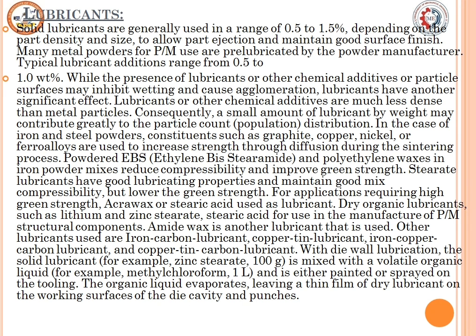Other lubricants used are iron lubricant, iron carbon lubricant, copper tin lubricant, iron copper carbon lubricant, copper tin carbon lubricant, and die-wall lubrication. The solid lubricant is mixed with a volatile organic liquid and it is either painted or sprayed on the tooling.